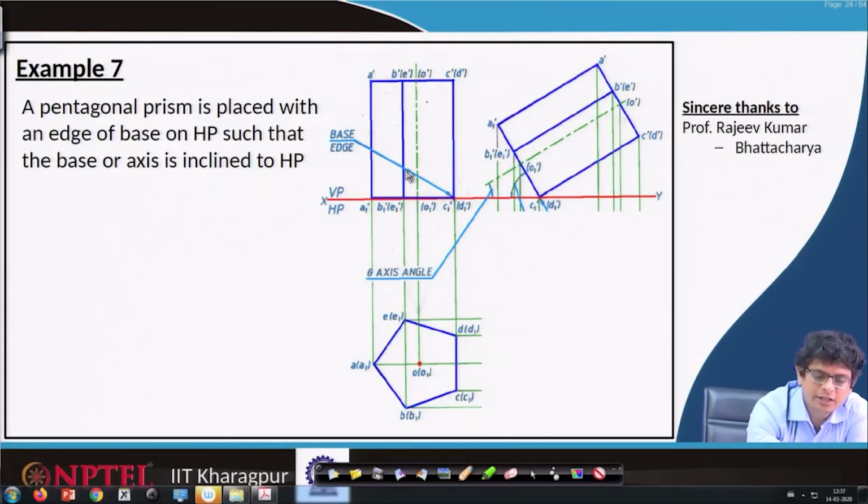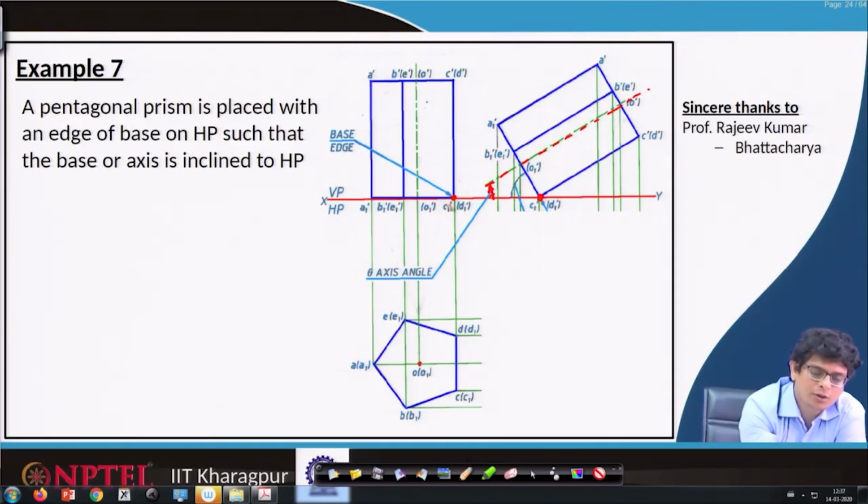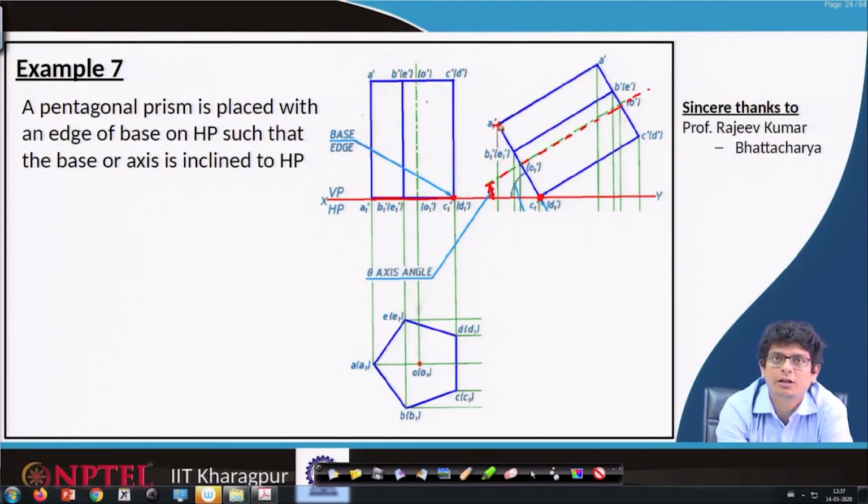So, when we do that, first of all we draw an axis making a certain inclination angle, maybe 45 degrees. It is rotated about this point, so this point always rests on that. Using our compass, whatever this distance, we make an arc of that distance perpendicular to this axis and join that line.